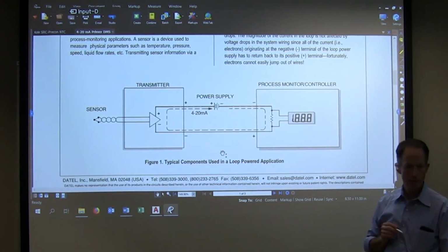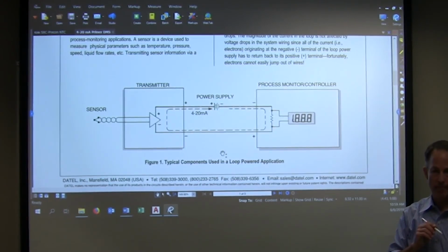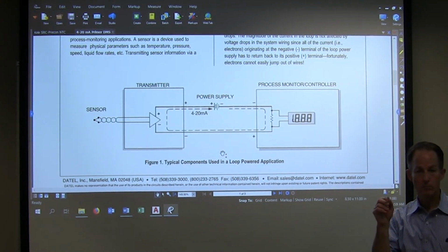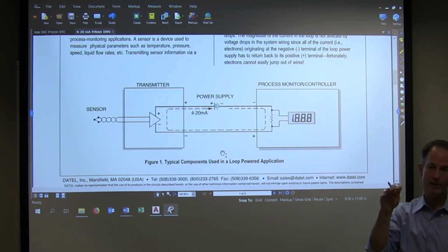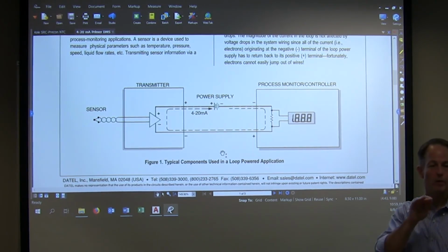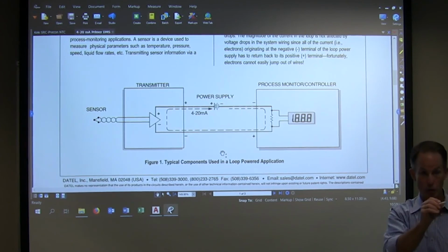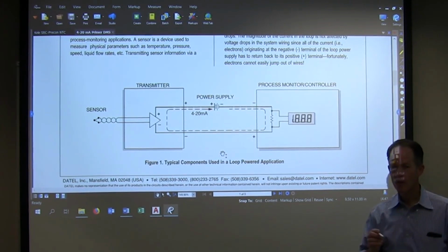There's another one: a clamp. An amp clamp, if you have a milliamp clamp. Or there's a way to wrap it. When you're dealing with milliamps, you'd have to wrap it 100 times. It would be a lot. Because 100 times would get us to 0.4 of a volt or 2 volts, right? Because we're 4 to 20. Sorry, we're doing milliamps, so it would be 0.4 amps to 2 amps if you wrapped it 100 times. But you're right, you could do that. You just have to have a really thin wire and patience. And count. Don't lose count.